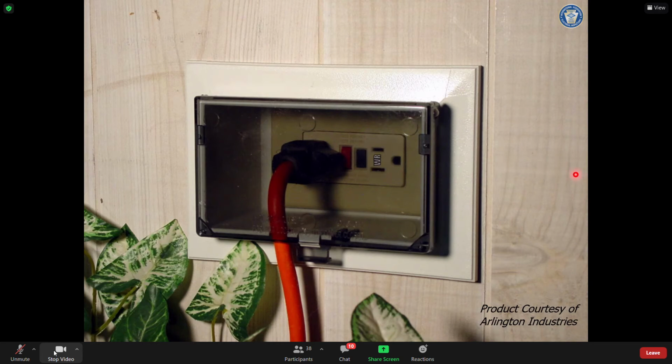designation. Is that a code requirement? Is it a code requirement that the manufacturer put WR on it? No, of course not. The actual receptacle has to be listed. The manufacturers are putting the WR on there as a convenience to you. It's not a code requirement; it has to come from the manufacturer listing.